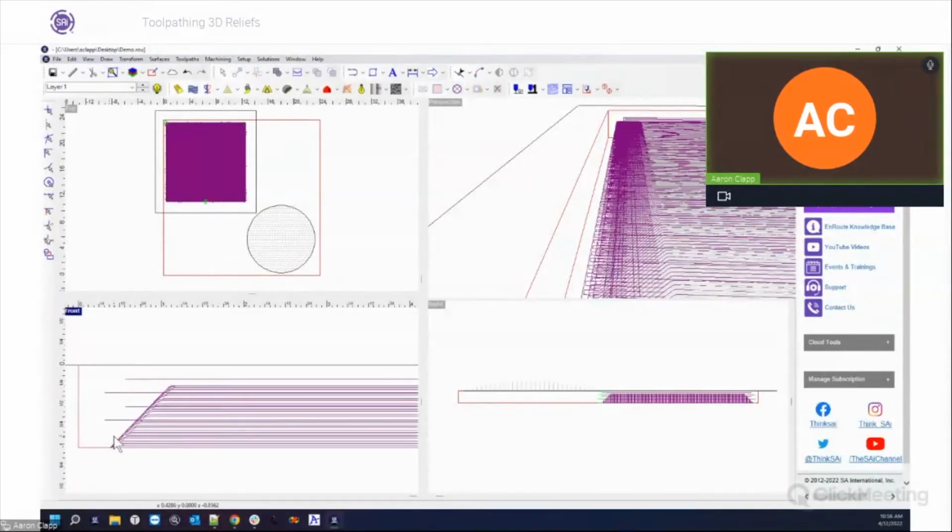That allows you to use your 1/8 inch end mill for the parts that are actually necessary, because it's going to be a real slog if you try to cut this whole thing out with a 1/8 inch end mill. You'd have to do it in multiple passes and it would take forever. This way, I can do my 1/8 inch end mill in one pass because I've already removed all the other material, and the amount of material I have left is minimal. So now I could just run my 1/8 inch end mill really fast, do the relief only, and then finish the part like that.